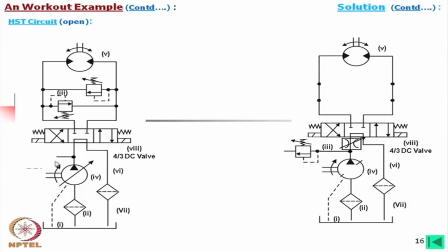Now, you should keep in mind, if there is a pressure setting, for example, the pressure setting we have seen is 7 megapascal. That is not 7 megapascal for agitating, but 14 point something for the maximum torque. So, it might be set at 15 megapascal. Okay.